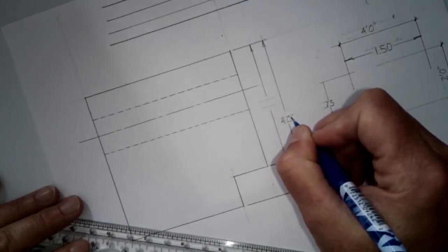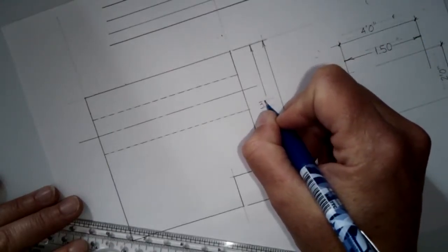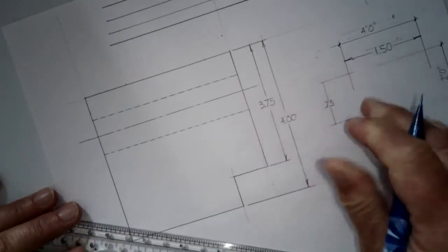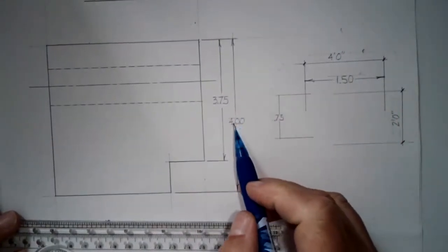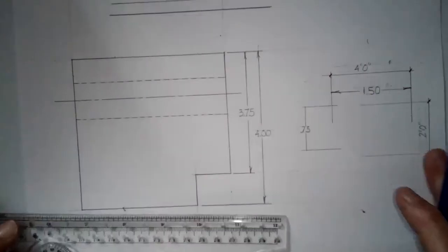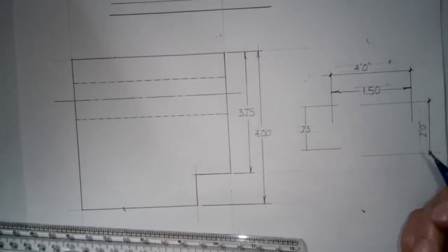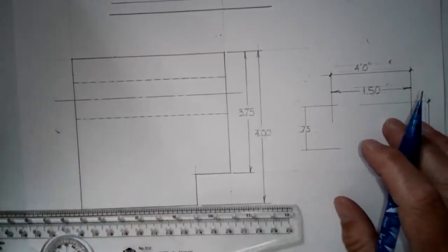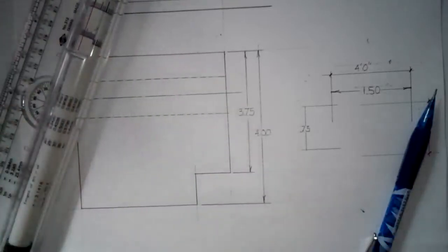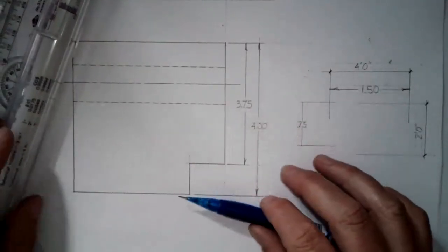So when you look at those dimensions and we put a dimension like 4, and we'll say this is 3.75, when you look at those two dimensions, they look the same size. And then, as from another lesson, you know the shape of all the numbers and letters has to follow that ANSI single stroke Gothic text type. Say that fast. So there are your lessons. I think this pretty much covers what you need to know to get started on the orthographic projection drawing and having an understanding of how to use these tools.